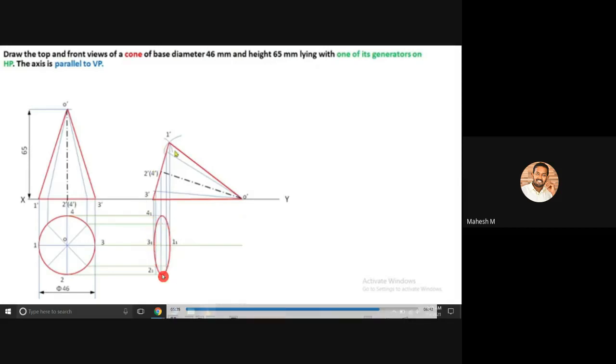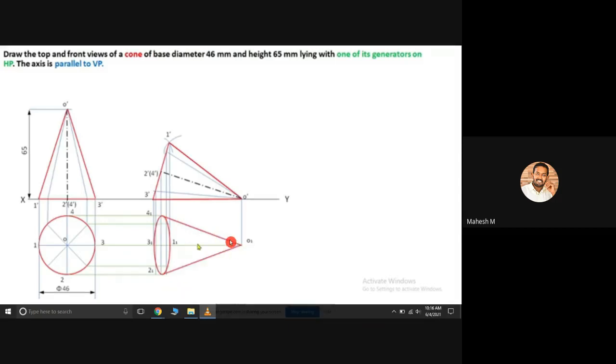So it should be a perfect ellipse. So the condition for a perfect ellipse is that you should not have any sharp corners. And also you can create your apex point in this horizontal line, because for O itself it is having 2 lines. So for O we are having a horizontal line and we are having a vertical line. So this is our apex point. So you can connect this apex point with 4 and 2. Okay, so this is our fourth diagram.